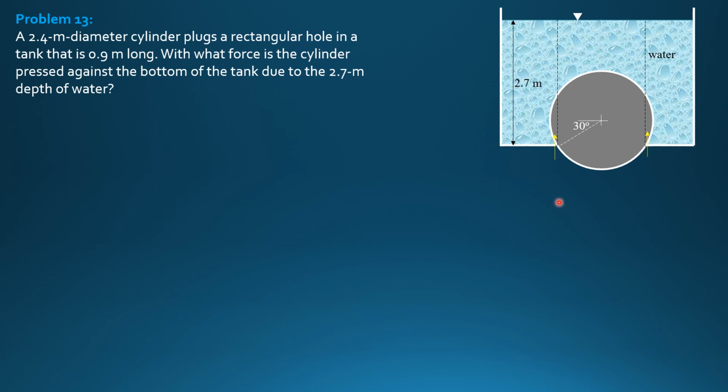So we will call that FV1. And for the weight of water above this curve, because these are the endpoints of the curve and we draw vertical lines up to the liquid surface, and it falls under case 1, the liquid is above the curve, so it is downward, and we will call that FV2.